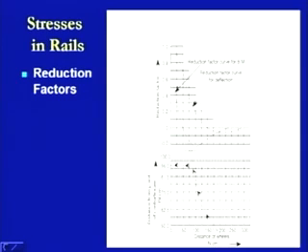So, we will be taking that value on the basis of wherever we are cutting this curve. So, if we are cutting this curve here, it means it is equal to minus 0.2. So, by this amount the bending moment will get reduced. Similarly, if we take the same value and we come to the top of this curve, that is the curve for deflection, then what we found is that the deflection will be getting increased by the value of something around 0.25 or so. So, this is the amount of deflection by which it will be increasing.